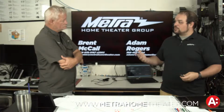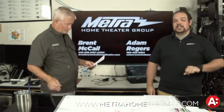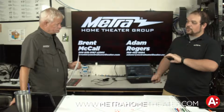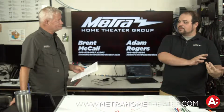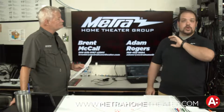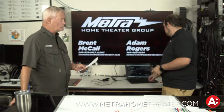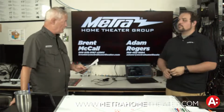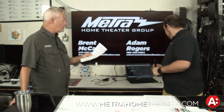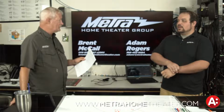Now, that does not include Ubiquiti. They have some devices that are PoE, their own kind of standardized PoE that is just on. It's always going to output power no matter what. It doesn't care. Be careful plugging power supplies, standalone bricks from one brand, into another device. Don't. Yes. So switches are generally safe and intelligent. Power supplies, bricks, maybe not so much.